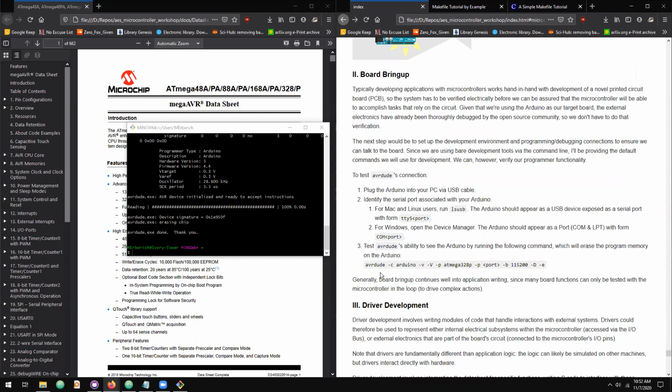Generally, there will also be more stuff here if you're using a dedicated debugger. A hardware programmer debugger also allows you to directly set program memory as well as inspect variables as your system is running. Unfortunately, due to the way the Arduino bootloader is set up, we can't actually use that debugging feature through the Arduino bootloader.